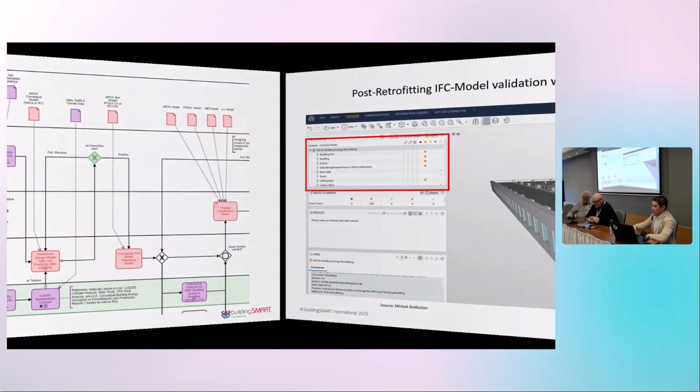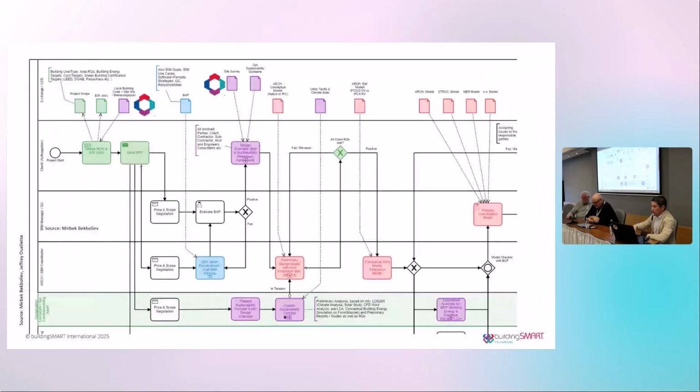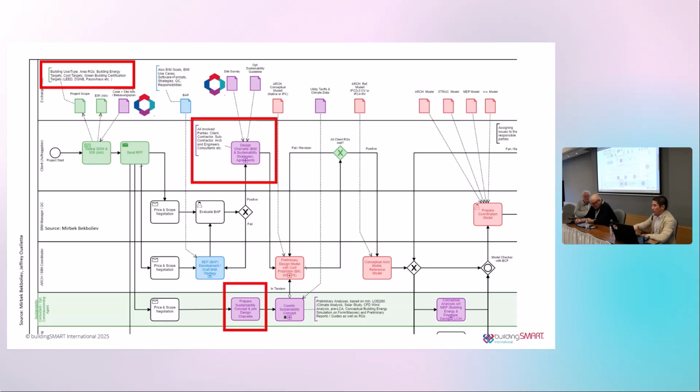And this is an extract from the BIM technical report. At the end there, as you can see, the process map shows that when you have your model ready for simulation, you run the simulation, you use the IFC model, and it should meet those requirements. Of course, it's also IDS, the general IDS, not for this specific project, the general IDS that says you also have to have spaces, boundaries, and so on, specific information like thermal energy related simulation values. Which we did not have at first. Yeah, we did. We had to work on that, so we managed.